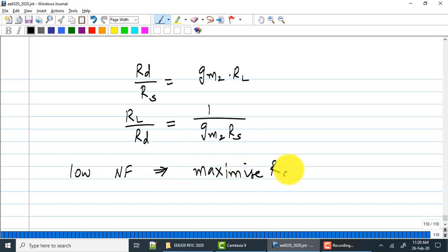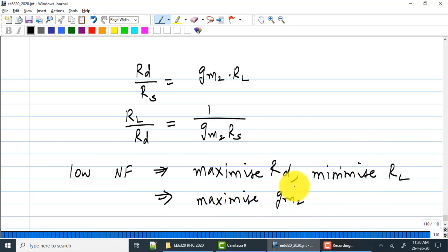So as you can see, in this LNA, the common source stage will probably be burning a lot of current, and will be much larger than the common gate stage, so that you get very large GM and you get low noise figure. And it turns out, of course, this noise cancelling LNA can achieve pretty good noise figures, definitely much lower than common gate stages. Any questions?